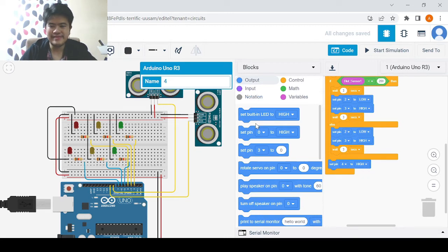And then before that, however, we have to put the yellow light, which is over here, which we know is pin number 3, to low. The same thing as what we did for the green light and yellow light. However, this time we have an additional step, which is for traffic light number 2, the red traffic light. As you can see, we go to anode, terminal 1 is at pin number 7. So we want to make sure that the LED for the red traffic light is low, or off. So we put pin number 7, scroll down, and make it low.